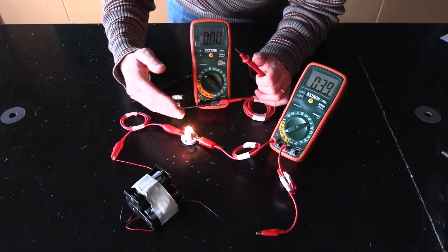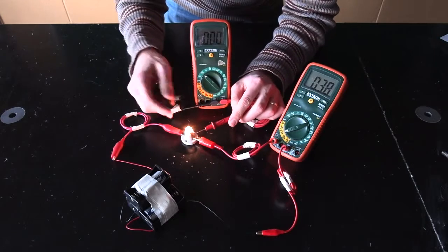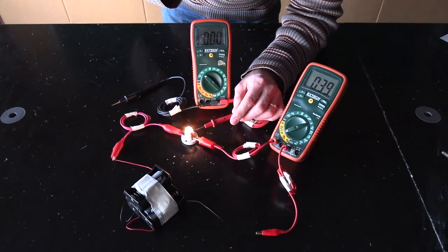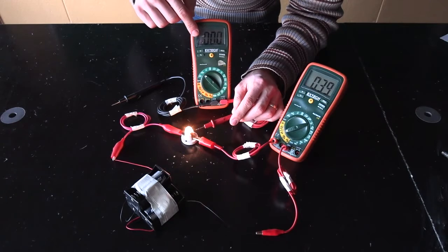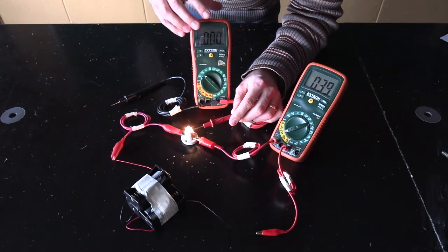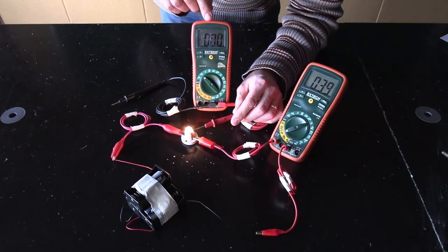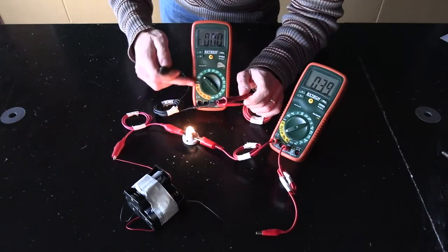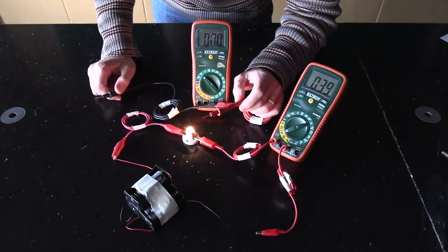We want it all to still go through the bulb and none to go this way, which means that the voltmeter now has to be built in such a way that it has a very high resistance. Ideally, you would want an infinite resistance. No such thing, though. So a typical voltmeter like this might be like 10 million ohms. So a little tiny bit of the current goes out and bypasses the bulb, but you try and minimize it as much as possible.